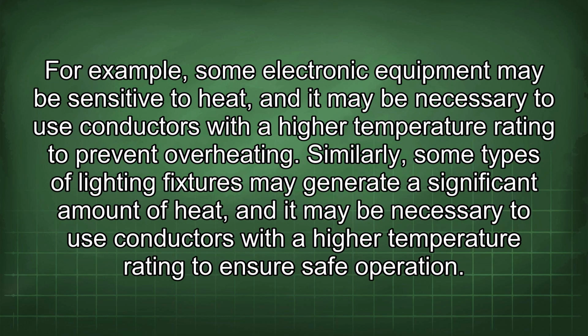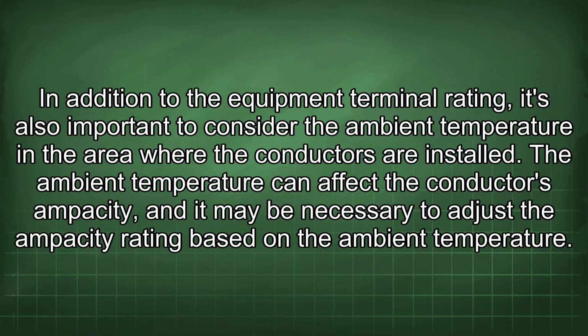For example, some electronic equipment may be sensitive to heat, and it may be necessary to use conductors with a higher temperature rating to prevent overheating. Similarly, some types of lighting fixtures may generate a significant amount of heat, and it may be necessary to use conductors with a higher temperature rating to ensure safe operation. In addition to the equipment terminal rating, it's also important to consider the ambient temperature in the area where the conductors are installed. The ambient temperature can affect the conductor's ampacity, and it may be necessary to adjust the ampacity rating based on the ambient temperature.